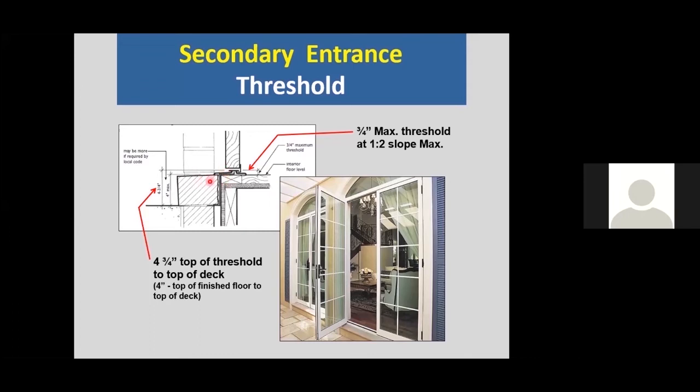So at these secondary exterior doors, HUD's guidelines allow not only this 3/4 inch threshold height from the inside finished floor to the top of the threshold, but they allow from the finished floor to the outside surface, if it's impervious, where water will settle and not drain through, up to a 4-inch completely vertical step down, for a total of 4 3/4 inches from, we'll say maybe a concrete patio surface, to the top of the door threshold.